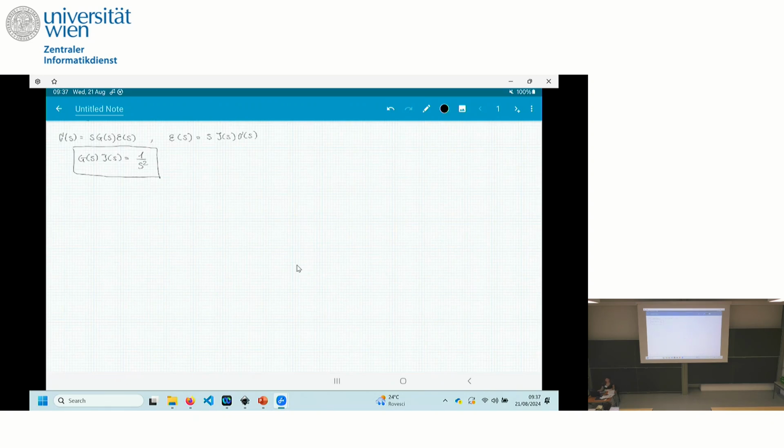So as we were mentioning, the third test is the dynamic test, when we apply a sinusoidal stress or a sinusoidal strain. Let's assume we are going to apply a sinusoidal strain, epsilon of t, and we write it as a complex number because that's going to be useful to derive the complex modulus.